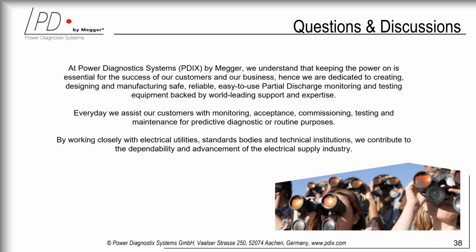So the first indication would be a level higher than this acceptance level, or a level higher than the noise floor level. So what we do, we calibrate the system in the field, and then we set the warning and alarm levels 30% higher than the noise floor, which should be much lower than the acceptance level that we know from the factory. It's the first indication.